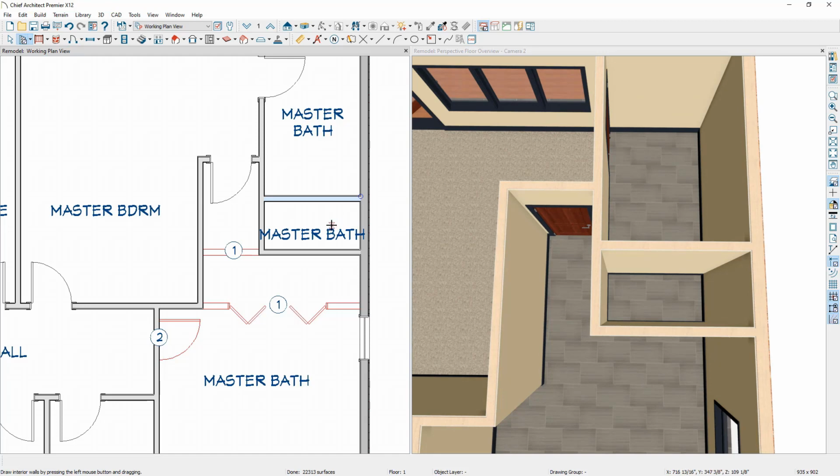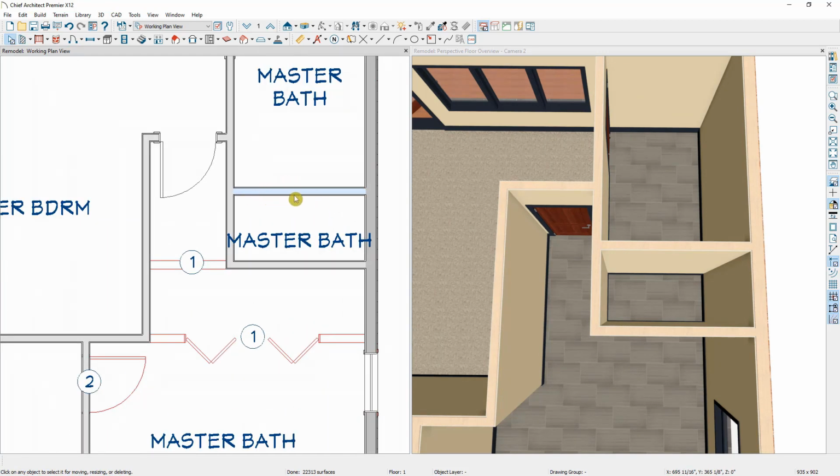And there we've formed another small room, and you'll notice that that wall type has a light blue fill based on our default settings. This just indicates that it's going to be a new wall type, and when we look at our schedules again later, this wall type will automatically be included in it. And I'm just going to go ahead and delete that room label for now.